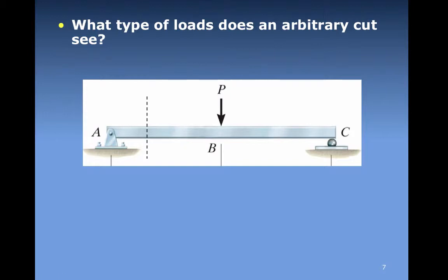You also know from work we've done in the past that if an entire body is in equilibrium, in this case the beam, we can take a section of that body and we know that it must also satisfy equilibrium. If we now take a cut section of this beam, where this indicates the line where we're dividing the beam, and we draw a free body diagram, our first rule is that we apply any of the external forces to the free body diagram, and of course that's our reaction force A sub y here.